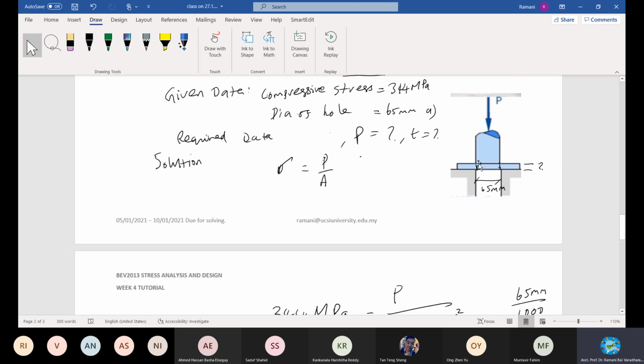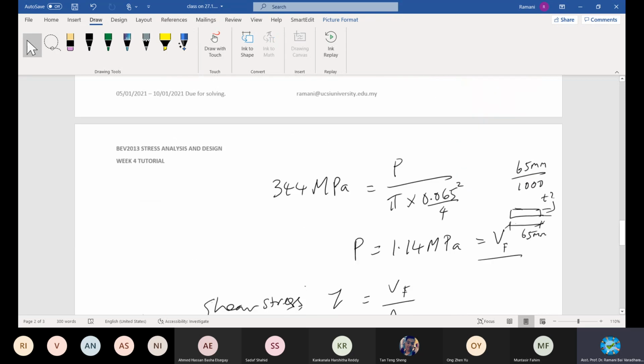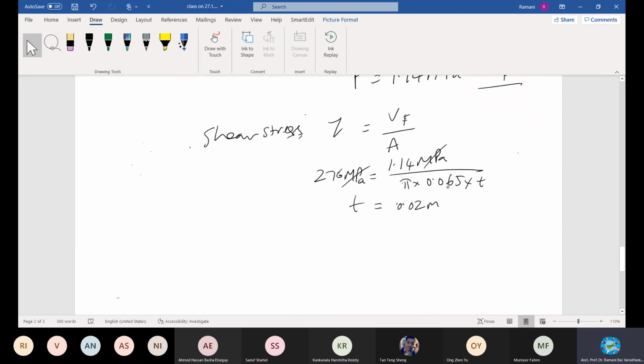The arrow is not coming here. This material will be sheared off when it is punctured, right? So I follow these dimensions of thickness and the width, T as my thickness and the width of this puncturing. I got the answer of 0.02. All are getting the same answer. 0.02 meter, 20 mm, approximately 20 mm. If you have points and all, you make it as approximately 20 mm.